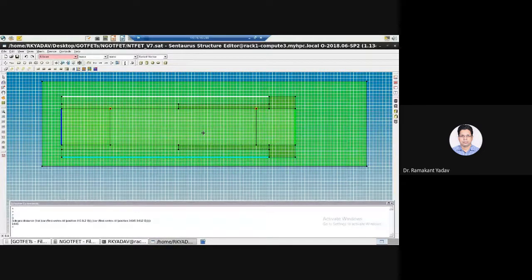So if you are designing the device in nanometers, you have to convert nanometers into micrometers. So this 45 is 45 nanometer, that is 0.045 micrometer. Similarly, the thickness of this device is 12 nanometer. This is the source region, this is the drain region. Interested students can go through the literature of the tunnel FET and MOSFET. You will find the device structure is almost the same. Only the source and drain doping are different. I will show you here.